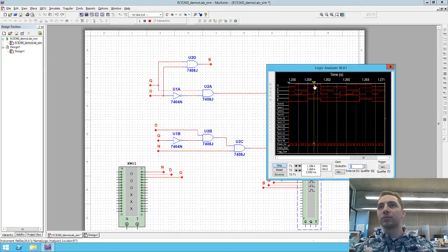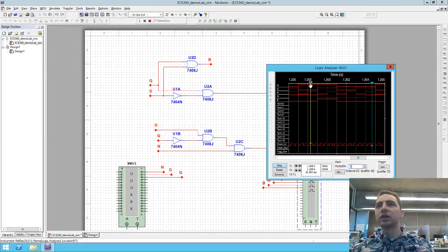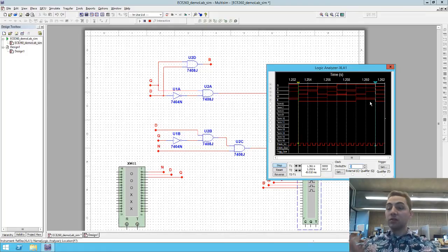All we really care about is the space between 0 and 7. After that, everything will repeat. So let's zoom that in. I think 2 is a pretty good approximation of what we need. There we go, so there's 0 and there's 2. And now we can look and say that W is going to be true in these 3 cases, but not in those 2 cases, and B will be true in those 2 cases. I'm not going to go into whether or not this is the correct functionality of the circuit. This is just how you're going to verify it. So you can now quickly check all 8 combinations using a logic analyzer.